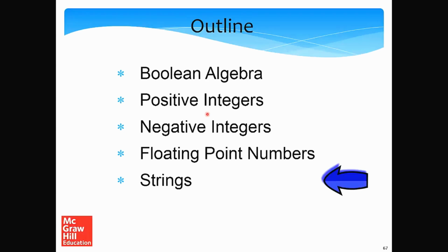So in this case, instead of going for a 2's complement representation of the exponent, we actually used a bias based representation, and we also used an explicit sign bit just to make our life easy, and also to leverage the pattern that you typically don't multiply the exponent. You would only multiply it when a number is being raised to the power of some other number, but that's a relatively rare operation. Most of the time we are only adding and multiplying floating point numbers. In that case, we do not per se multiply the exponent.